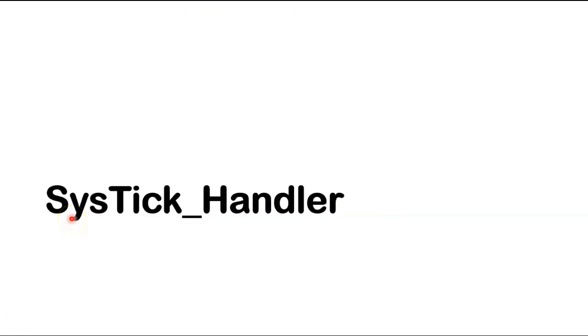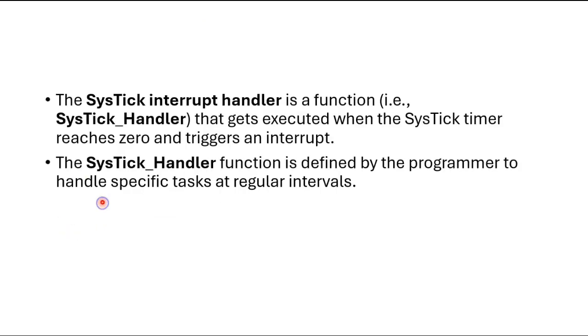SysTick handler. Now the SysTick interrupt handler is a function that gets executed when the SysTick timer reaches 0 and triggers an interrupt. Now the SysTick timer handler function is defined by the programmer to handle specific tasks at regular intervals.